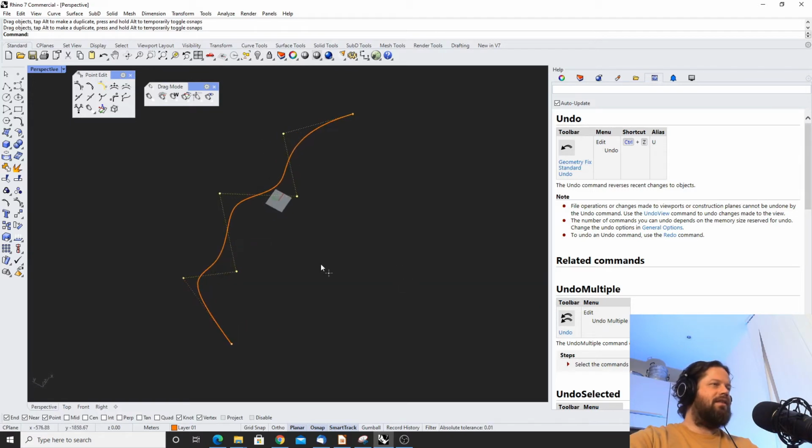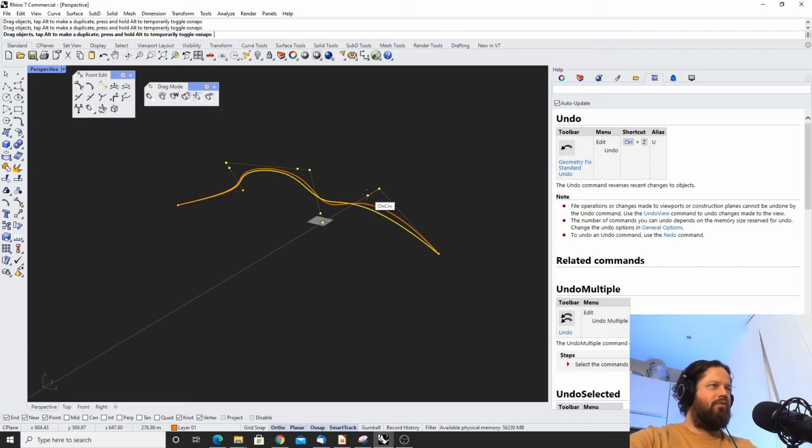You can see that this line is shorter than this one. So when I use the shift command, it will move only proportional depending on the length of that control segment. When I don't use shift, then that's what it does. When I use shift, it moves the absolute amount. Sorry. So when I use shift, it uses the absolute amount I'm moving in the first segment. I could also use, of course, another one here. And if I don't use shift, it only moves proportional depending on the length of each segment.